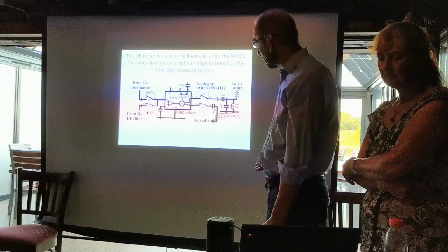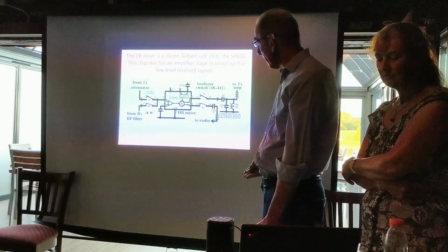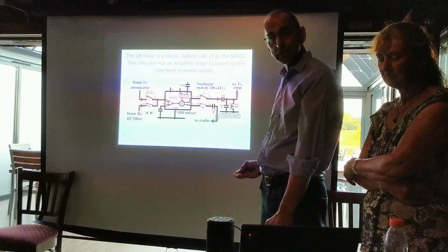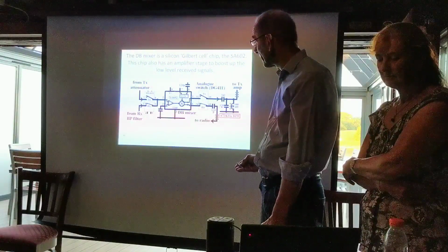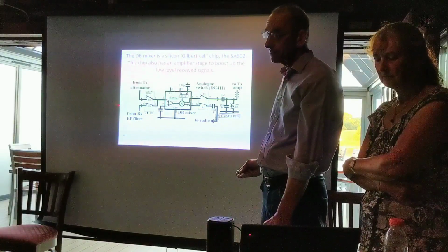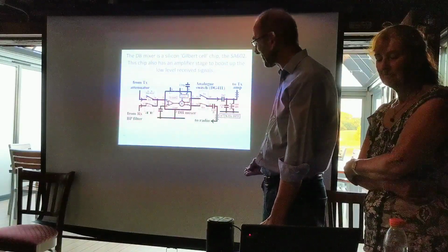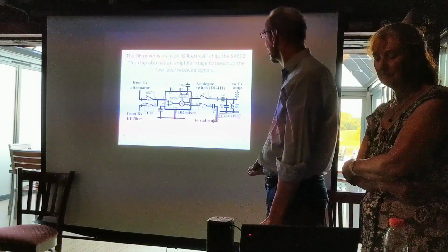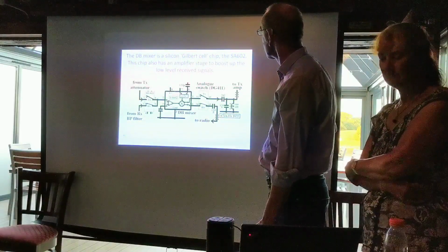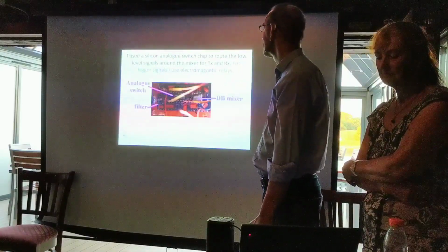Now, obviously this has to go in one direction for transmit and the other direction for receive. And I've used analog switches for this. Relays are okay, but the contacts can get dirty and they can become unreliable. Analog switches never go wrong unless you overload them, in which case they blow up very well. So they're ideal for using around a mixer where the signals are small. And that's that little parallel tune circuit bandpass filter, that same old configuration you've seen so many times.